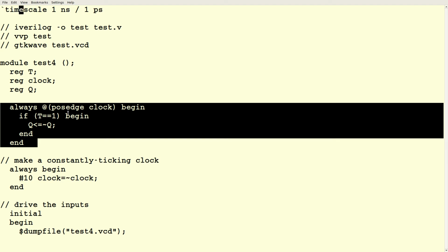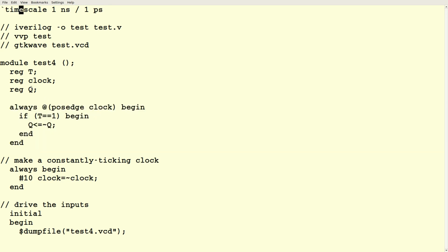Yeah? So you're using a register there in the homework. They're building a JK flip-flop and they use wires. Yeah, so you could do this, well, there's got to be a register somewhere, though, that's probably being assigned to the wire. There's a register for the output. Yeah. So I could call this something other than Q, and I could make Q a wire, and I could assign Q equal to that internal thing. But ultimately, something's got to be able to remember in between these clock ticks.